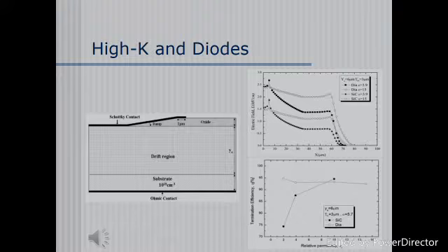By using high kappa dielectrics, we can decrease both the electric field inside the oxide and the chance of premature breakdown of the dielectric. As the relative permittivity of the dielectric grows, the electric field in the oxide falls, and as a result raises the breakdown voltage of the diodes. The ratio of the experimental breakdown voltage and the theoretically ideal breakdown voltage, called the termination efficiency, jumps at a large rate for bigger values of relative permittivity, independent of the angle ramp.